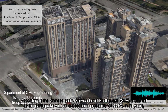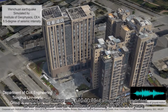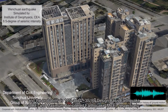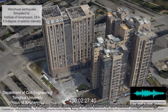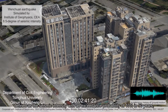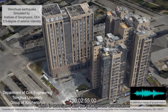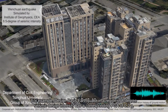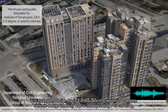According to the Chinese code, service level earthquake is defined as the earthquake with an exceedance probability of 63.5% in 50 years, and the probability is 10% and 2 to 3% for design basis earthquake and maximum considered earthquake, respectively. The intensity of design basis earthquake is also known as the seismic design intensity, defined as the seismic intensity with an exceedance probability of 10% in 50 years, which is associated with a peak ground acceleration. For example, design basis earthquake in a region of 8 degrees seismic design intensity has a corresponding PGA of 0.2 g.